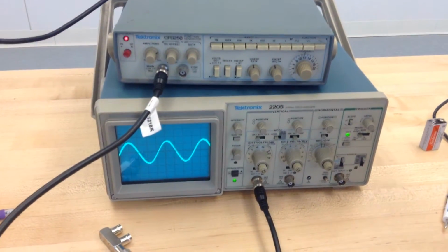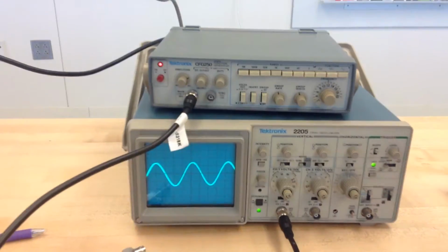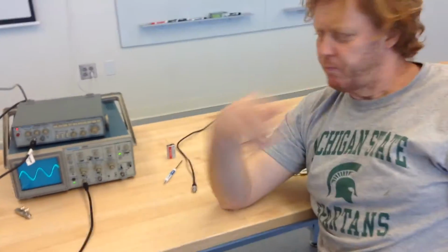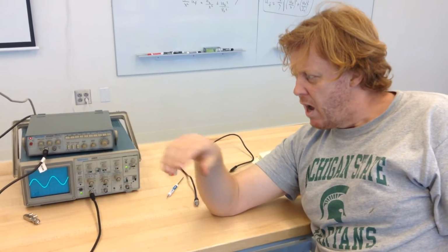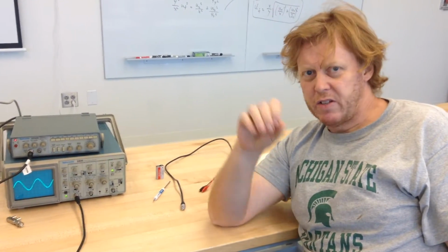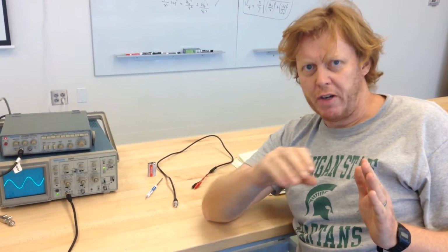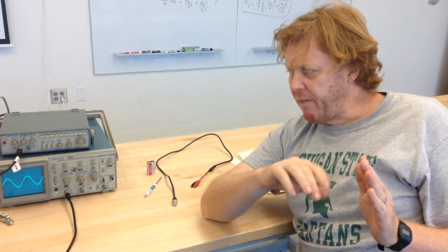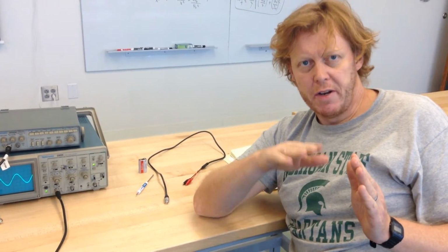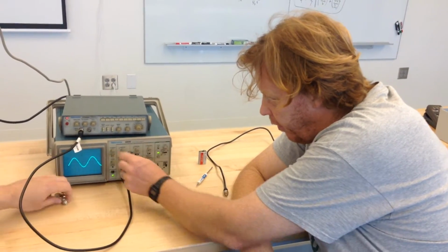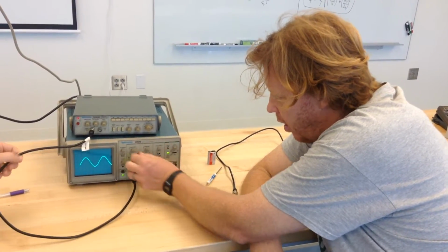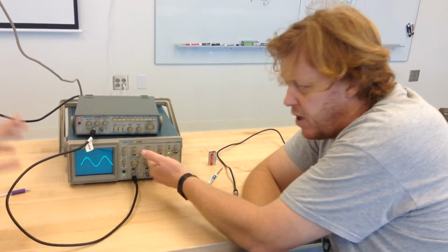Now, we're talking about triggering now? Yeah. Okay, so now the question is this. Here's a signal that's happening 1,000 times a second, right? The oscilloscope starts redrawing this picture. You have to time when you start redrawing it to get a nice crisp picture. I'm going to move the position of the signal over to here. See, I can move it left and right, or I can move it up and down. You move these to suit yourself.